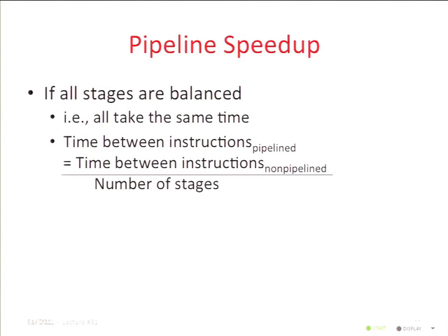So we're not neglecting clock-to-Q and hold time. That has to be factored into the clock tick. You have to be able to finish, from when the clock starts, the clock-to-Q delay, and make all that work. If we put registers in between, wouldn't that add some time? It's a good point. This is being a little sloppy. When you put those registers in between the stages, you are introducing a slight delay, because remember, registers have setup and hold time, and they have clock-to-Q delay, so you have to factor those in too.